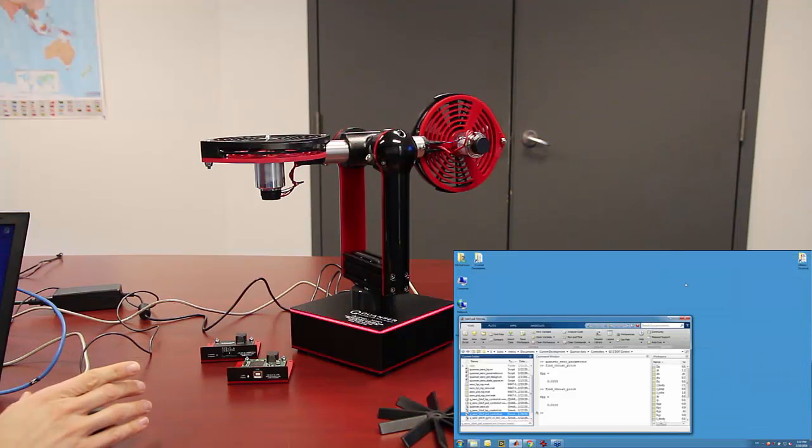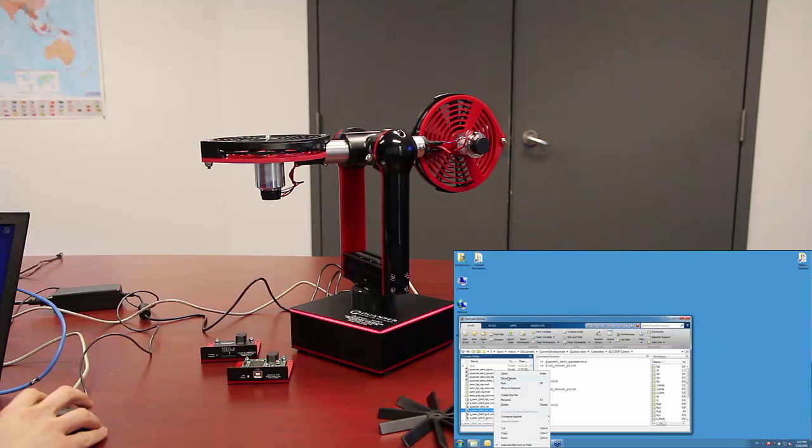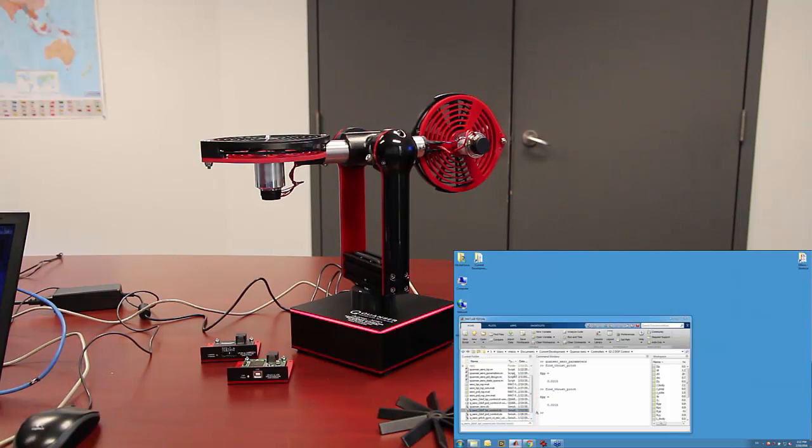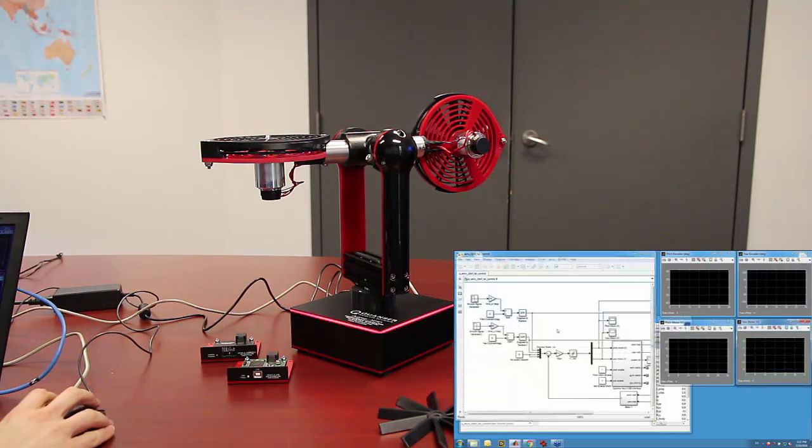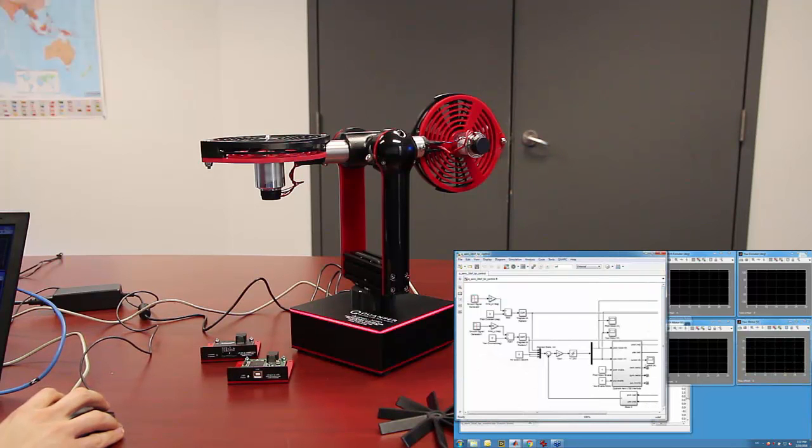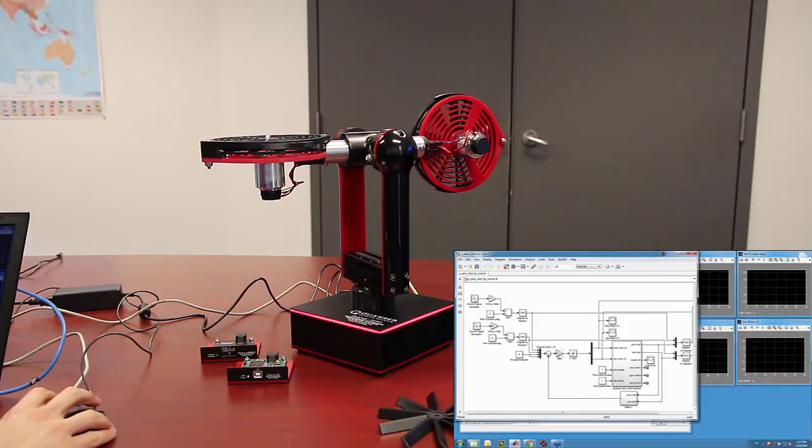And note as well, when I'm running the controller, the LED light was changing as well. So now let me show you a different approach. This is using a state feedback controller, which is a coupled design. The model that was based on deriving the gain, using the linear quadratic regulator method, or LQR, was based on a model that does have this coupling effect. It takes that into account.